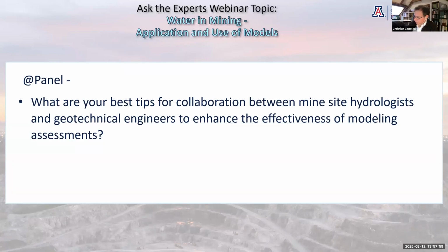Geotechnical engineers will just run with the pressures that they use. They'll probably typically use a phreatic surface with a hydrostatic distribution. We know that's not the case. So one of the important things we need to do as hydros is educate geotechs around variability in pore pressure profiles and why it changes in a 2-dimensional or 3-dimensional system, and really work with that.